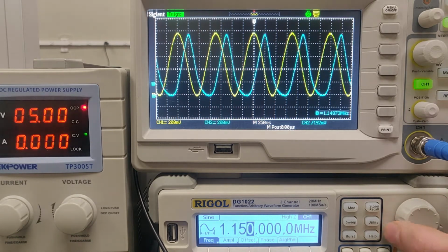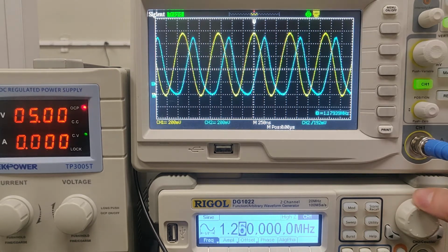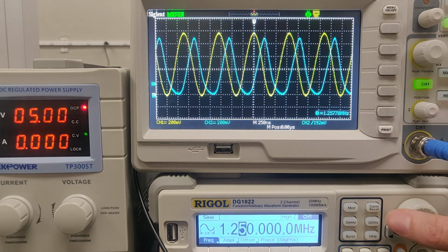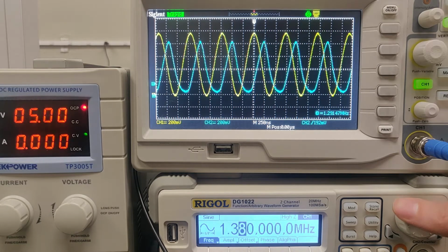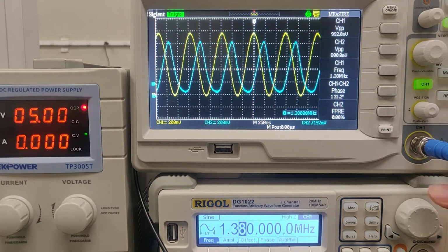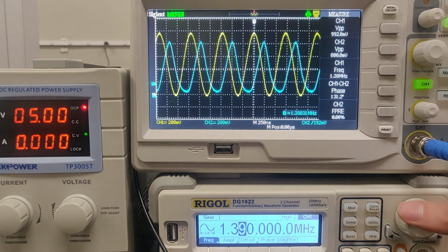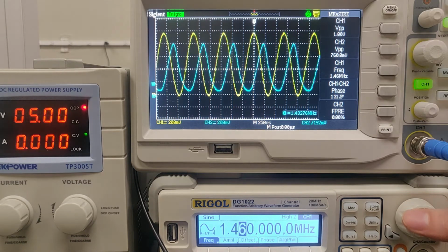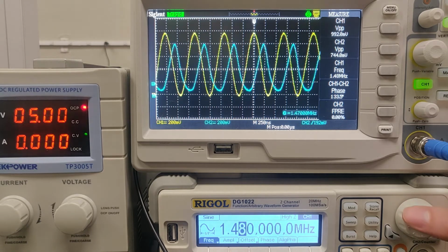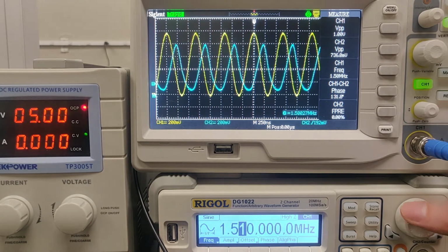Let's see, or maybe even 10,000. I would say definitely around here is when our peak is starting to, our output amplitude is getting noticeably smaller than our input. So let me get the measure going just to get a rough estimate. And again, our ratio should be 0.707, and because our input is roughly 1 volt, it should be around when our output is